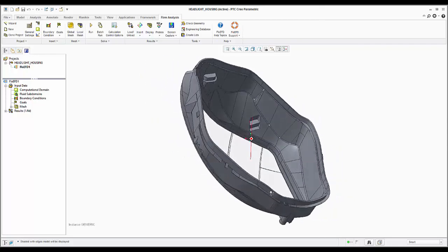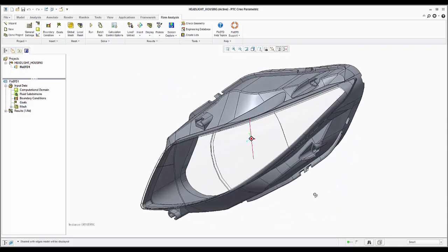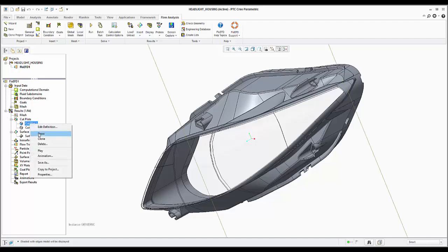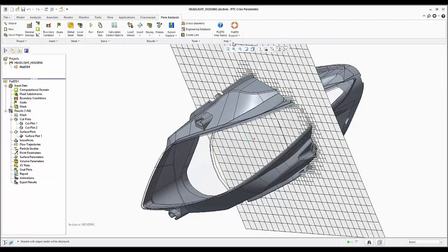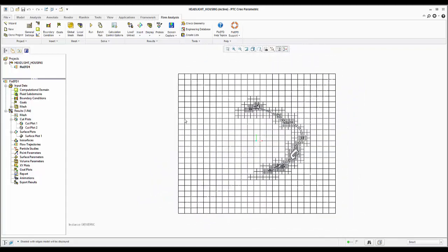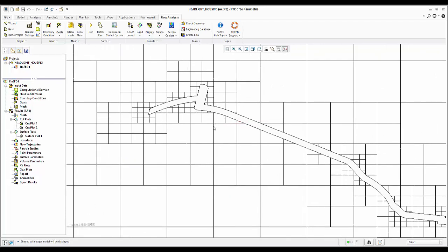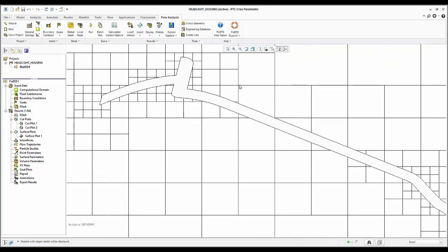The second key feature is the ability to handle complex arbitrary volume solids using immersed boundary Cartesian meshing. Here we have a motorcycle headlight unit which we wish to mesh. FloEFD handles this complex shape very quickly using automatic or manual mesh settings. FloEFD uses a Cartesian meshing schema, which can be seen here with increasing mesh density levels closer to the volume. FloEFD also has the ability to handle multiple control volumes within a single cell. This cell has 3 control volumes.